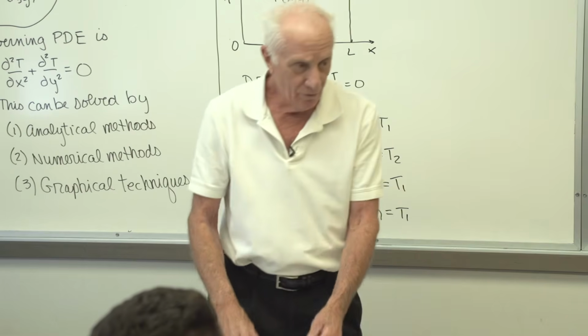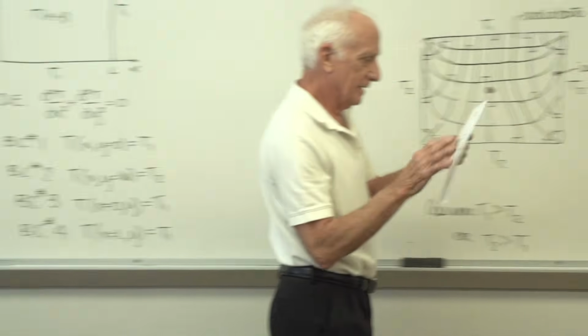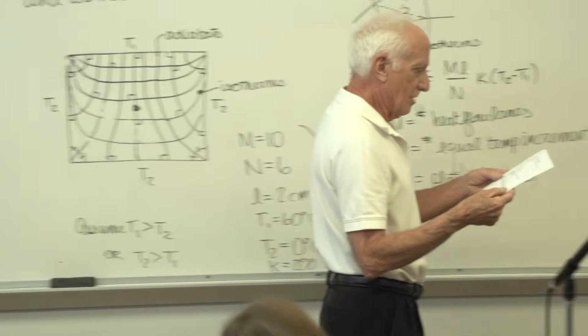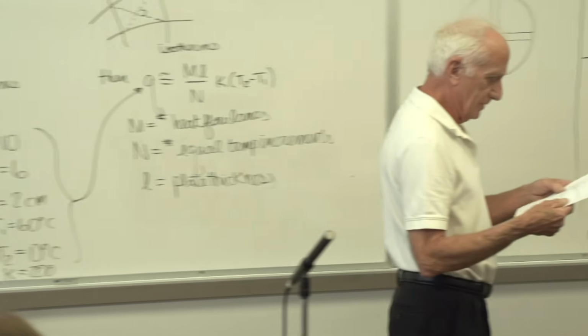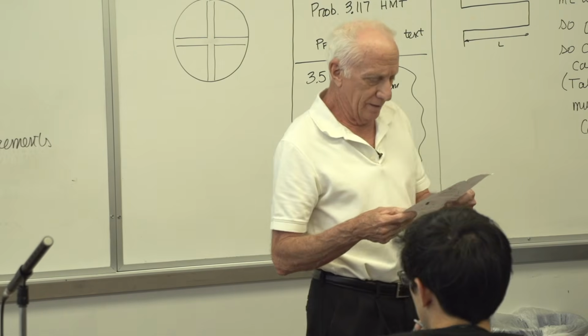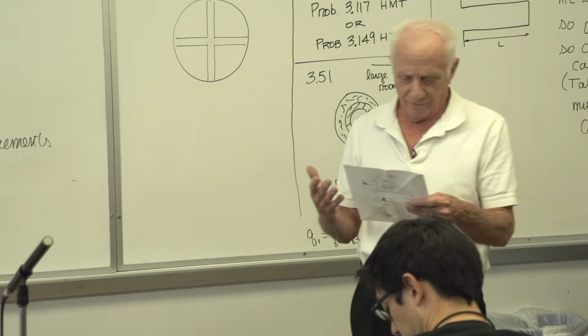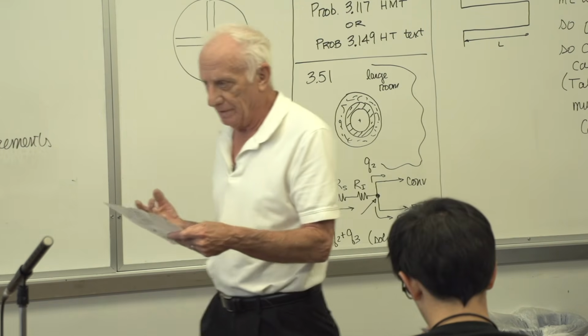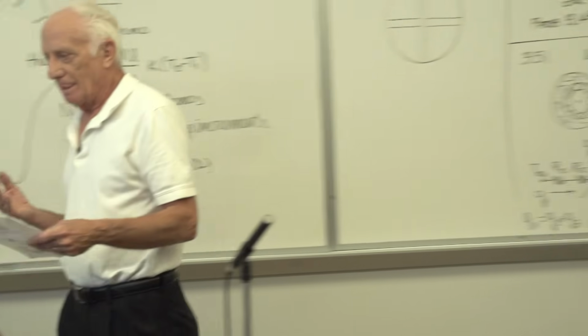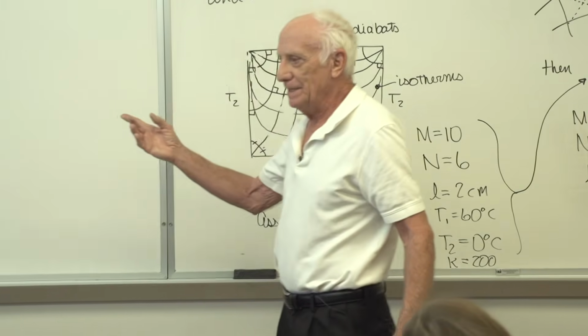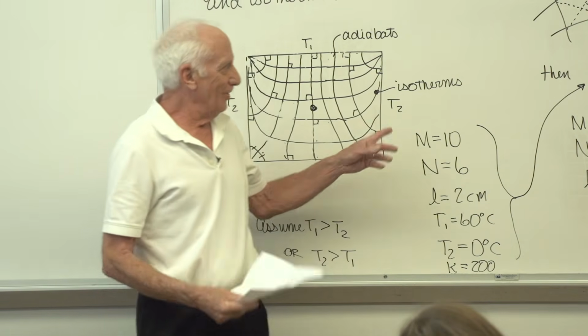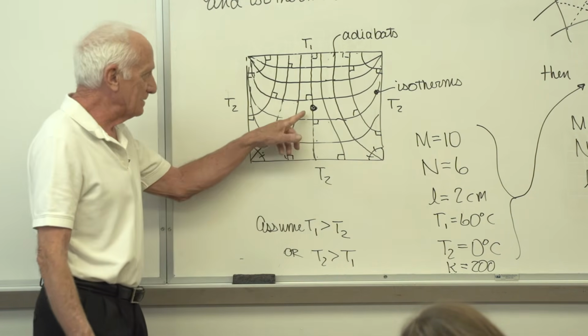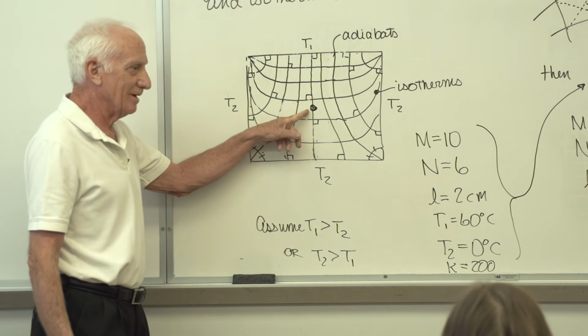So what? Well, the so what is at the bottom of the page here. It says, the graphical approach has 2 important uses. Number 1, it develops an engineering intuition for the temperature field and heat flow in many 2D conduction problems. I don't need to solve the PDE to make that really good drawing. I don't need to get the estimate of 26 degrees to solve this.